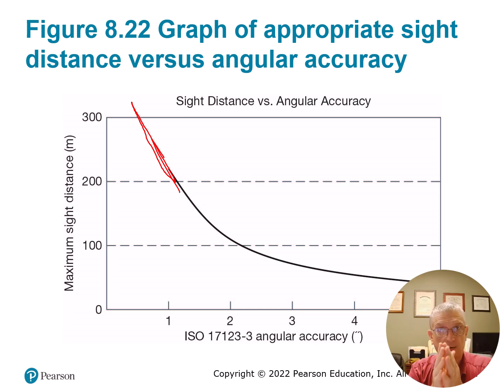We're talking about how much that angular measurement makes. The further out you get, it makes a whole millimeter in a 200-meter sight. So you can read theoretically a second of arc pretty well. You can discern a millimeter's width. It's like a crosshair at 200 meters. But at 20 feet away, that same millimeter might be a minute and a half.